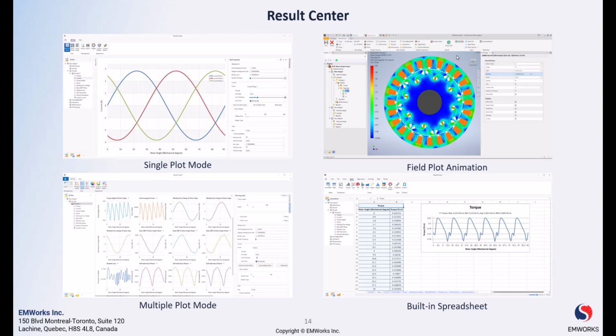These visualization panels are fully animated for transient simulations as well. So you can simply scrub through time using the built-in animation controls to see how fields evolve over an electrical cycle. The visualizations are also interactive. You can pan, zoom, rotate, and even take accurate measurements of geometric entities or quantitative values right within the 2D view.